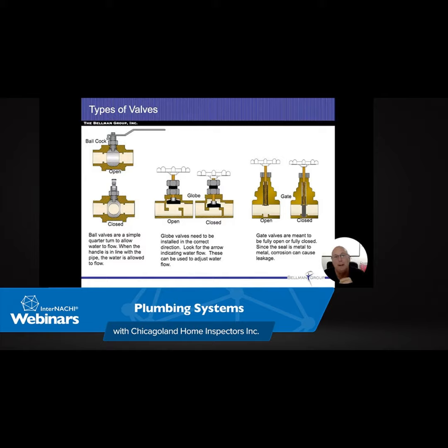But now if this is leaking and I have to replace it, the only place I could turn the water off to this house is out in the street. And I need one of those Buffalo box keys in order to do that. So I would have to get the water department out here or a plumber that has one in order to shut that water off and replace that valve.